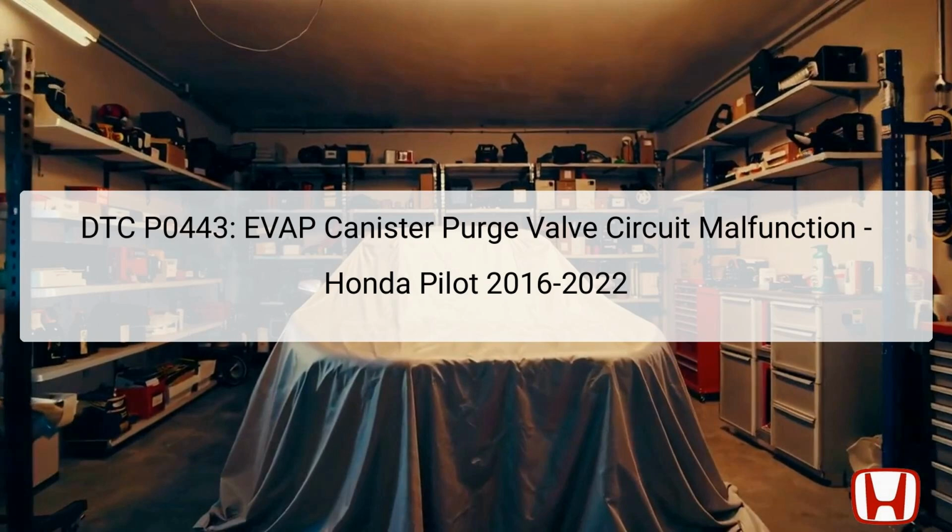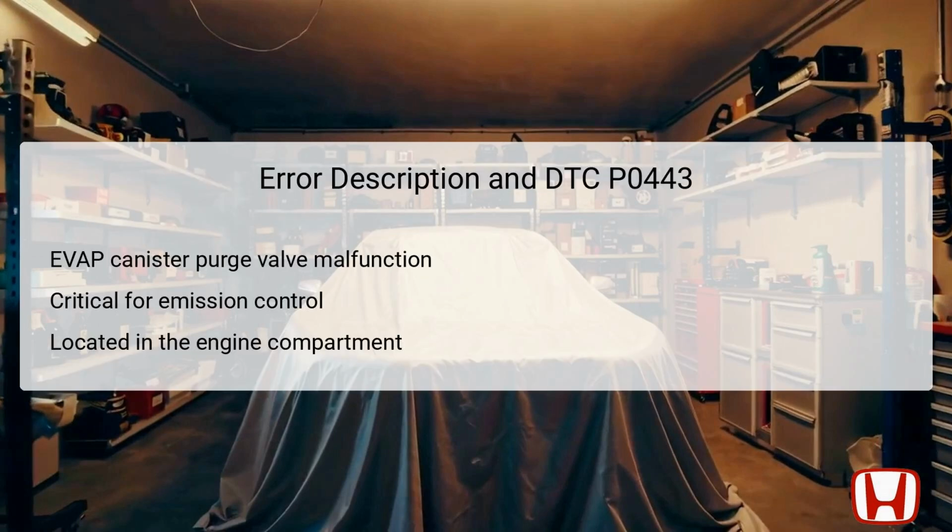The purge valve is usually located in the engine compartment and plays a vital role in the overall functionality of the vehicle's emission system. If this circuit malfunctions, it can lead to a variety of issues, including failed emissions tests, poor fuel economy, and potential engine performance problems. The DTC P0443 points to a malfunction within the EVAP canister purge valve circuit, which is an essential part of the vehicle's emission control system.